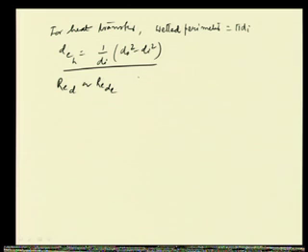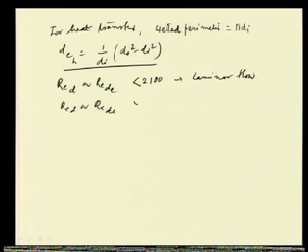if this is less than 2100, then we call the flow a laminar flow. Then if RED or REDE, D meaning based on equivalent diameter, is greater than 4200, we call it turbulent flow.